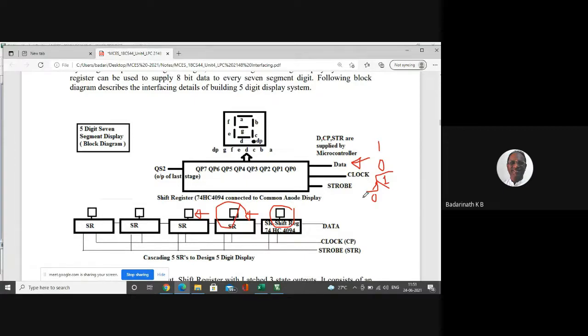That means that always before entering this program, keep the clock line 0. Then in such cases, you apply the clock. Since we know that in the beginning, by default, the clock line is 0, you can immediately apply 1, because previous to this program the clock is always 0. We can make that assumption. Keep the clock line 0, make it 1, keep it for some time as a delay if required, then make it low and leave the program. This is also equivalent: you're preparing a transition. But always we are assuming that the clock is at low.